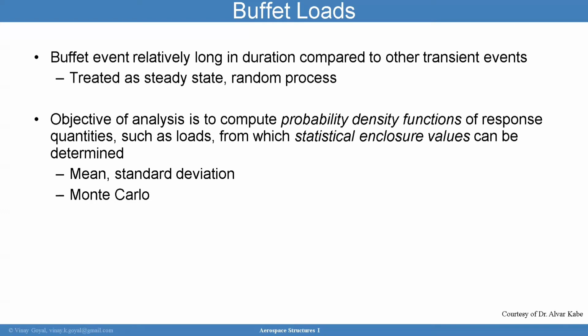So in reality, the buffet analysis is performed to establish the loads due to the dynamic response of the vehicle payload system to shock waves, flow separation due to changes in vehicle geometry, and the interaction between the two. For most vehicles, the analysis is performed in the frequency domain, and the forcing frequencies are described in power spectral densities.